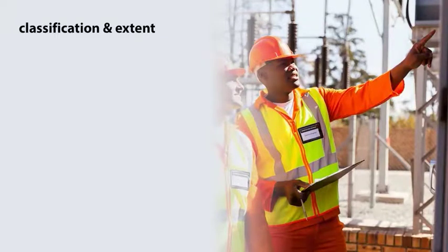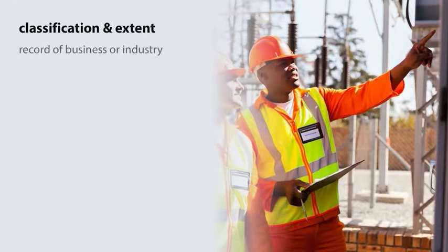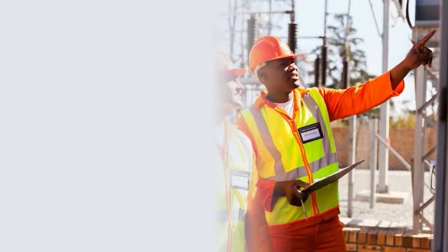To determine the classification and extent of any hazardous location, you must take several factors into account: the quantity and type of flammable material that might escape in case of an accident, the adequacy of ventilating equipment, and the total area involved. Also, it's important to have the record of your particular business or industry examined with respect to explosions and fires during the use or handling of flammable materials. You must thoroughly consider all these factors before setting any hazardous location parameters.